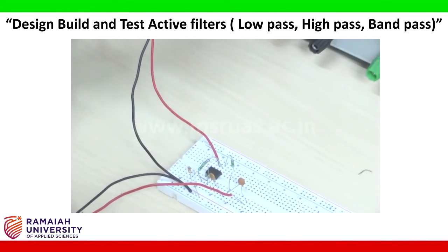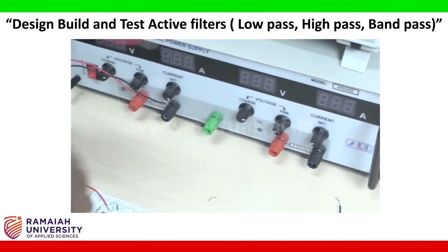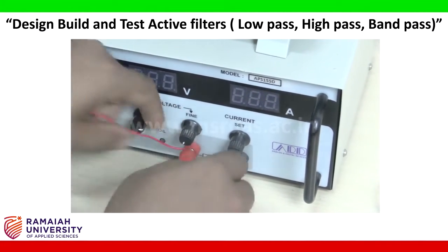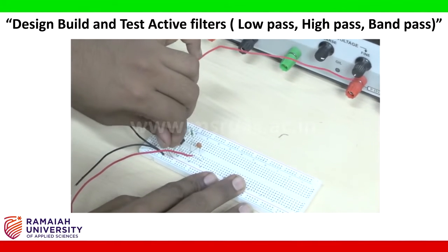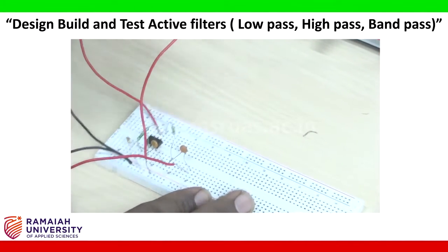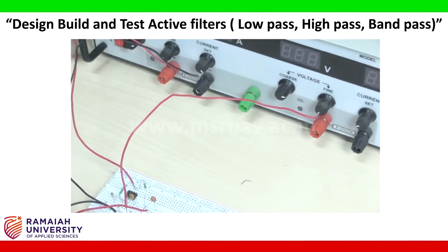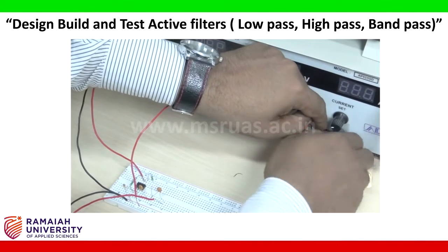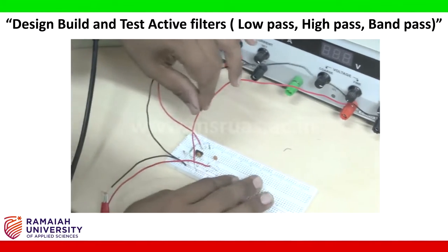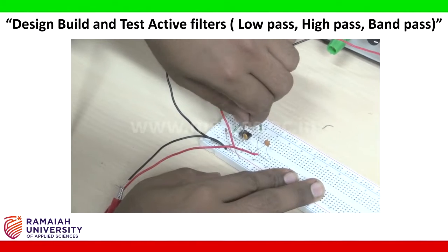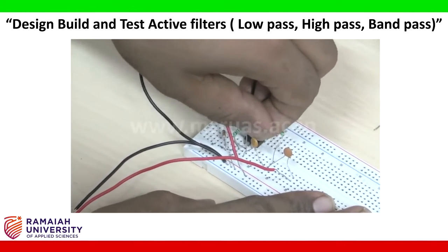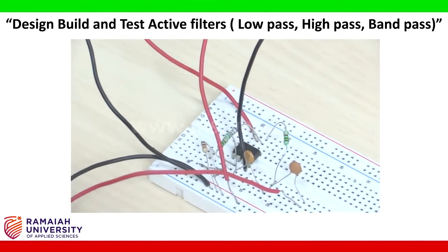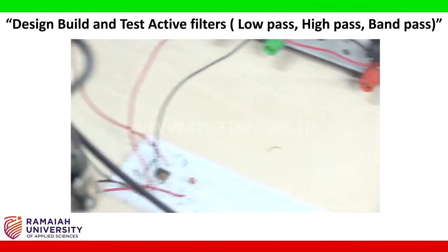Here, another terminal I am taking, the positive, I need to put it into ground. This positive I will make to ground. The negative end will be given to pin number 4. This negative end I will give to pin number 4. This is pin number 4.